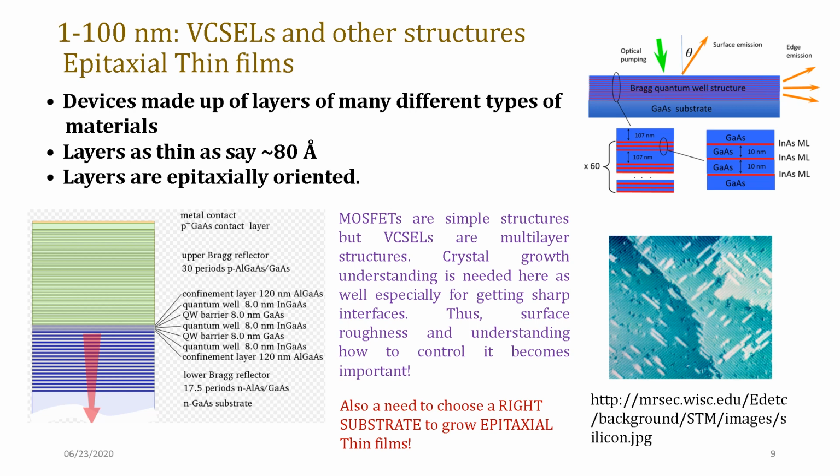We are talking about 10 nanometer or few nanometer thicknesses of different stacks, where we have indium arsenide in between and then gallium arsenide, indium arsenide stacks. And how are we going to deposit them? And what is this going to do? We have layers as thin as 80 angstrom that can be deposited, and these also can be epitaxially oriented.